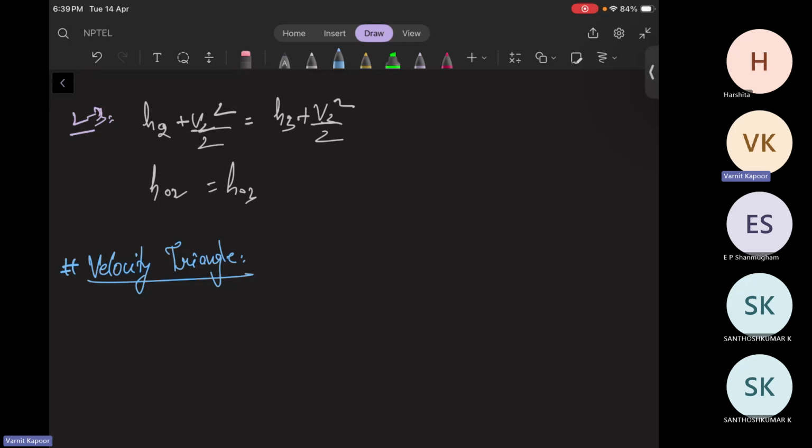So let us assume that at the inlet of the impeller, fluid is always entering in a radial direction. When I said that at the impeller, it came axially, it was not completely axial. It had some V1 absolute velocity, which had a component of whirl as well as an axial flow direction. So let us say that the whirl component is completely zero.